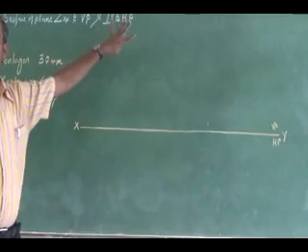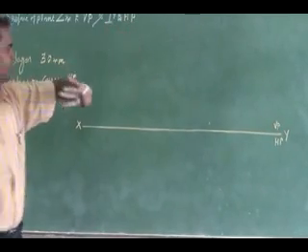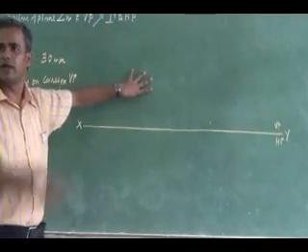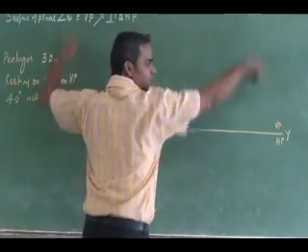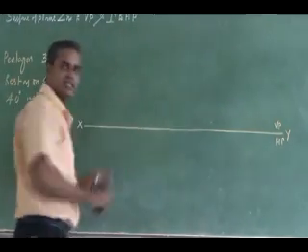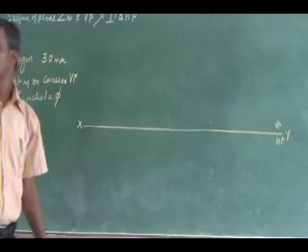On the vertical plane, since it is inclined to the vertical plane, I am making it align on the vertical plane. So this is going to be my vertical plane, above the reference line. That is nothing but the front view. There I have to draw my true shape.